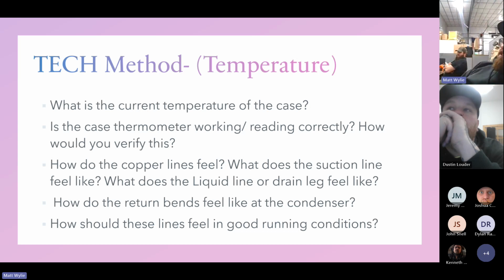Costco called last week and they said their dairy cooler was 63 degrees, and I got there and looked at the thermometer hanging on the wall, and it's like 60, 65, but it didn't feel like 65. I got my probe, and my probe was reading like 32 to like 35.